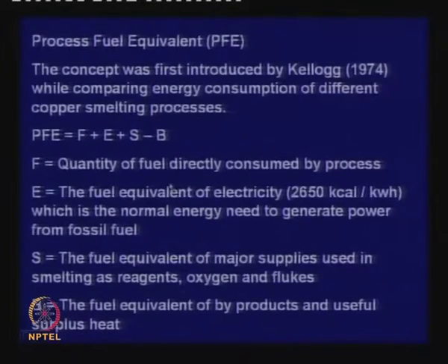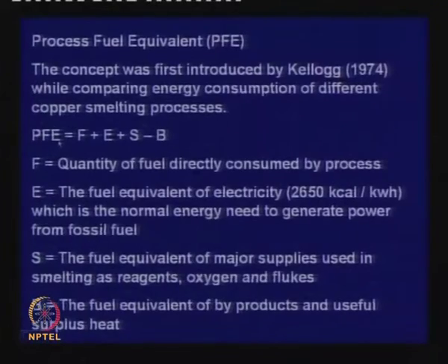The concept of process fuel equivalent, to which I am coming quite frequently, is very important. It is vital for analyzing any metallurgical step. The process fuel equivalent, PFE, is the quantity of fuel directly consumed by the process, plus the fuel equivalent of electricity that we may be using in the process. So, these are the energy inputs.